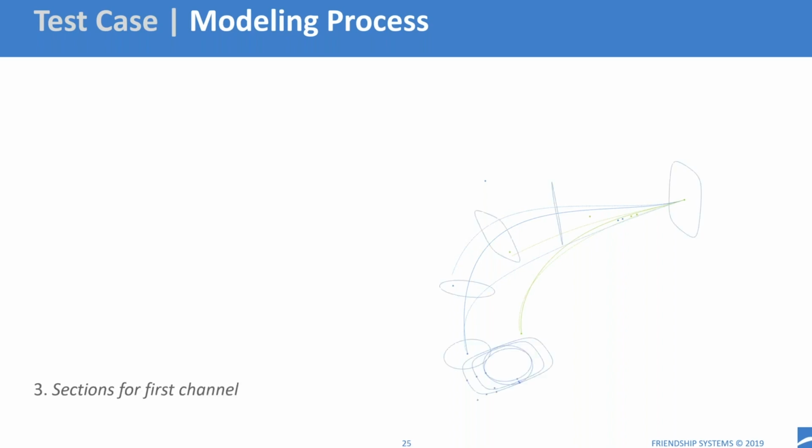And then we can place sections along this channel, and we have different methods of modeling such surfaces in CAESES. One option that one can use is a parameterized cross-section that is basically swept along the path or in a certain direction, and then during the sweep you can control the parameter values of this cross-section with a function that describes, at each position along the path, what the parameter value is.